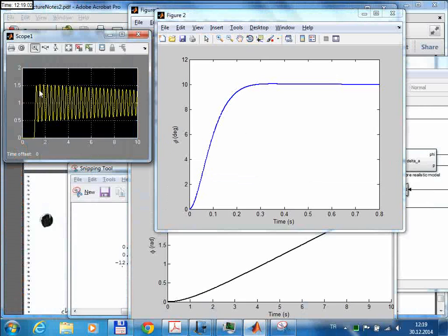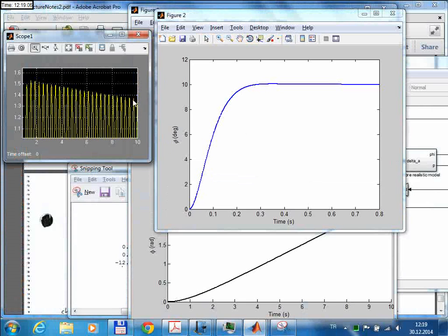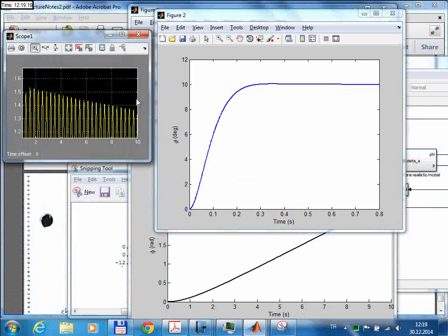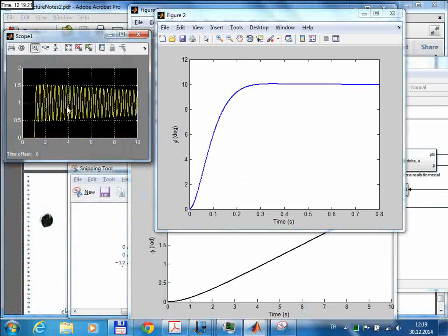What we get is stable, but far from our expected transient dynamics. So this is unfortunately what we get from the Routh-Hurwitz test, since it only gives us yes or no information for stability; we find the boundary for stability. And obviously this is not an acceptable autopilot design.